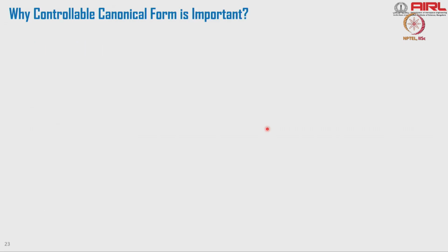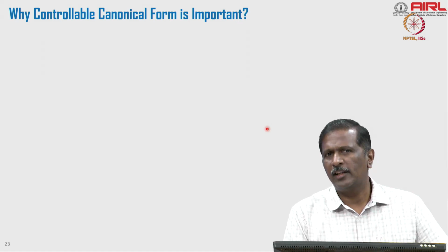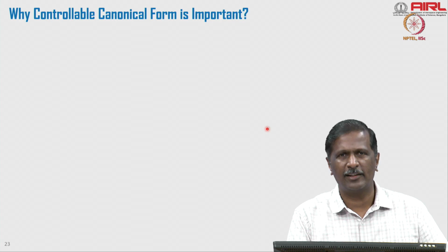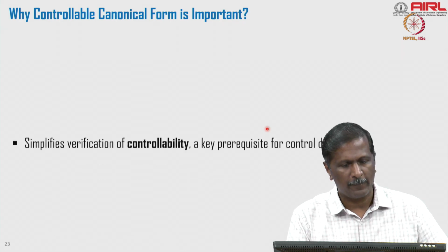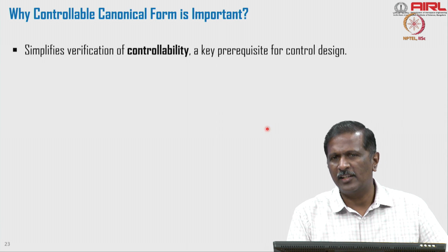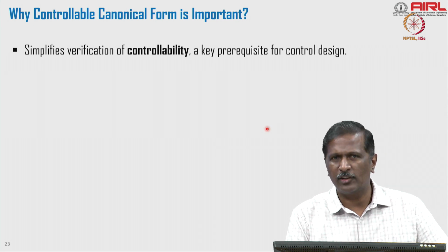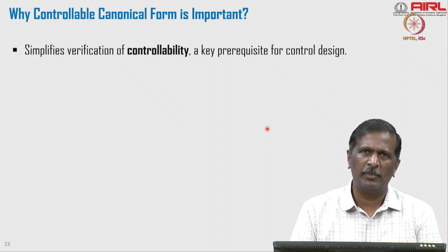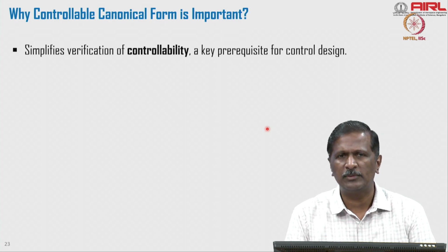Okay. Why is controller canonical form important? Why do we focus only on controller canonical form, right? It simplifies the verification of the controllability, right? Controllability is an important test, right? What does controllability say? All the states of the system are controllable.